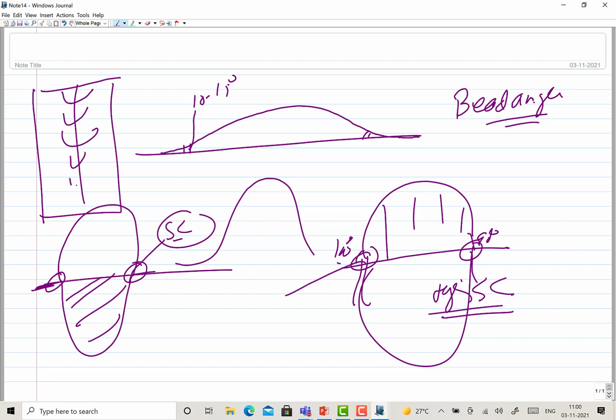Rough means there are a lot of ups and downs in the weld bead, so these will be acting as stress raisers and weld discontinuities. A rough or irregular weld bead causes high stress concentration, leading to poor joint strength.